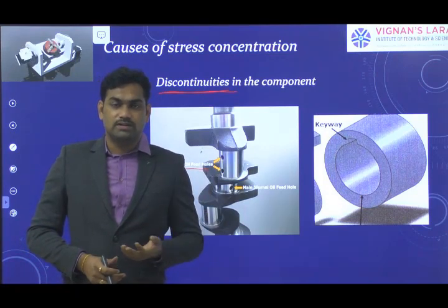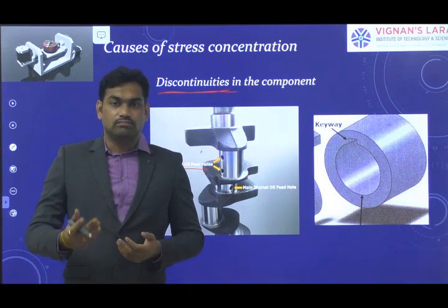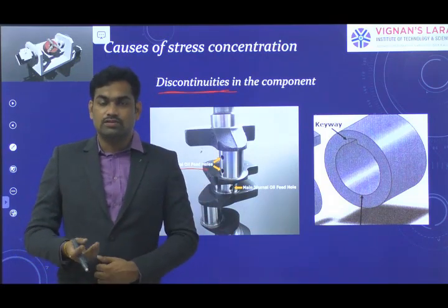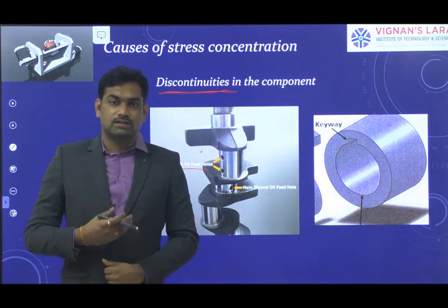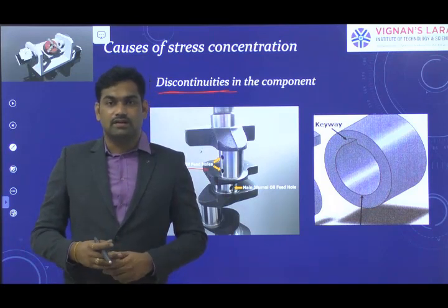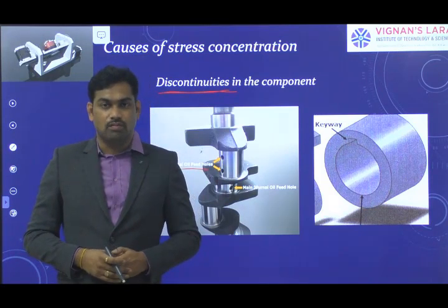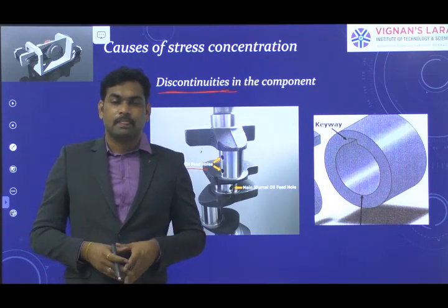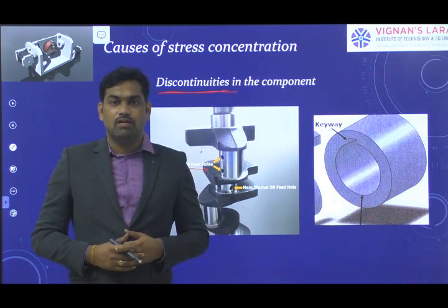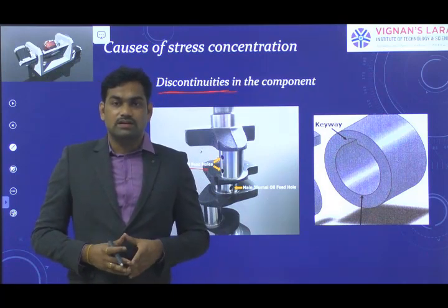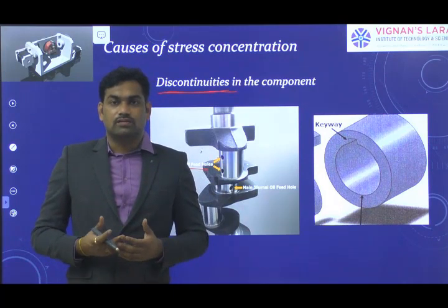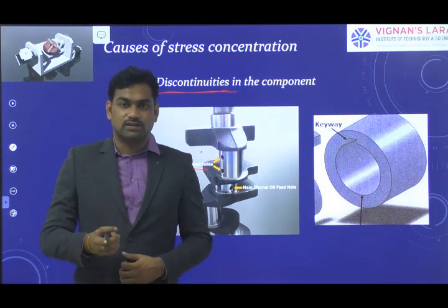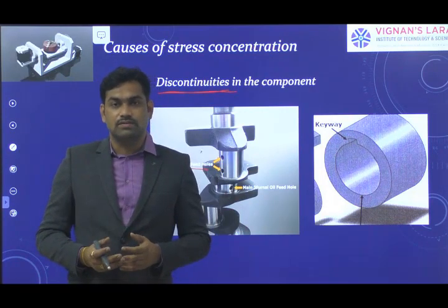Coming to the second one, discontinuities in the component, oil holes or keyways you can provide. The third one is load application, and the fourth one is sudden changes in the component. All of these are causes of stress concentration. Clear? But in a machine component, it is not desirable to have stress concentrated at some particular areas, which will cause damage.